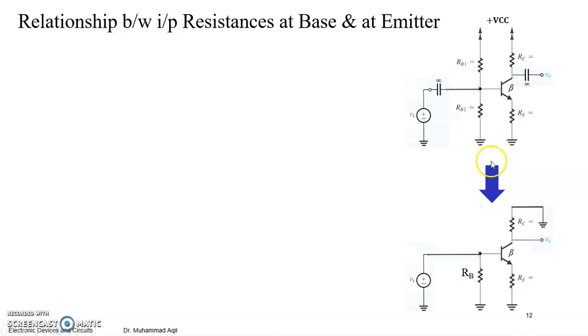And for AC analysis, we make an AC equivalent circuit, that is how this circuit looks for this input AC signal, right? And then we saw that part of this AC signal will become the AC VBE, which will be superimposed on the DC VBE and make some amplification at the collector side, right?